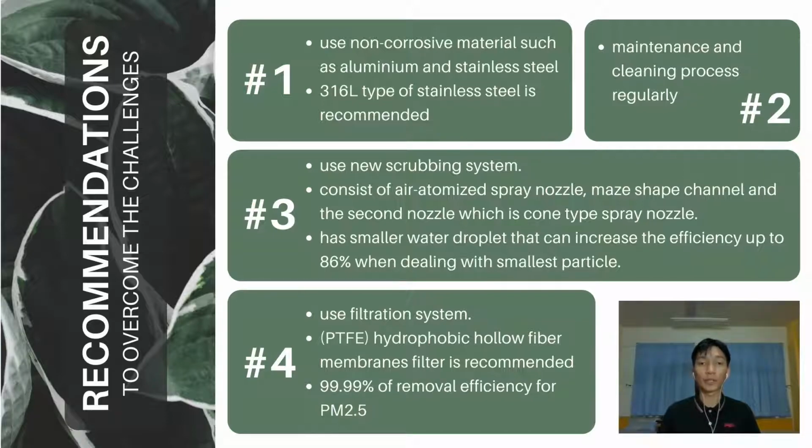Next is installing a filtration system at the sludge stream, for example, a PTFE hydrophobic hollow fiber membrane filter. The cleaner water byproduct can be used again in the water diffuser, or it can be disposed of freely as it is clean and safe for the environment.